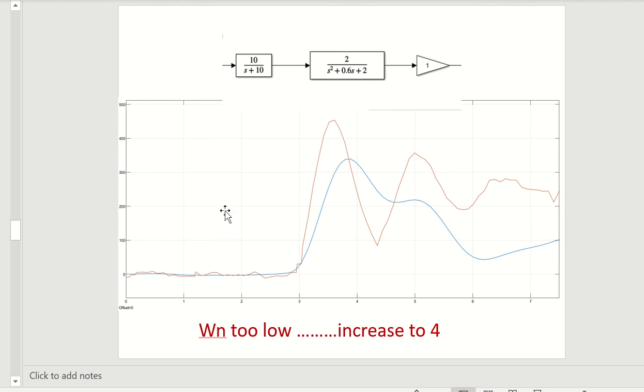The best way to do it is to use this number here first to shift the red line up, so that it ends up roughly the same point here. So we'll need to shift the red line upwards by making that number bigger. So make that number a bit bigger, we can shift this up. That's the first thing to go for, is get the steady state of both matched up.